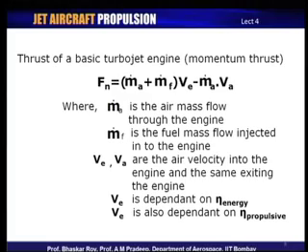For the moment, let us say we will ignore the pressure thrust, assuming at least for the moment, that the pressure reached at the exit phase is equal to the atmospheric pressure, and hence we just at the moment ignore the pressure thrust component and we have only the momentum thrust. And then this momentum thrust now has two components, one which is of course the exhaust reaction, or what we had called the gross thrust.